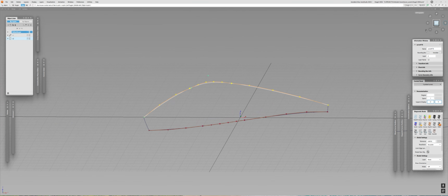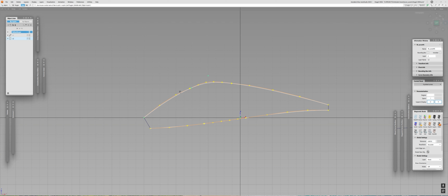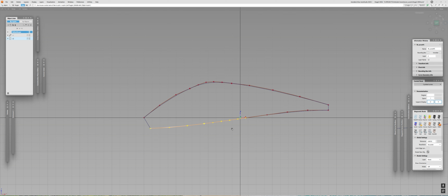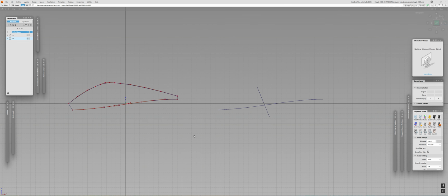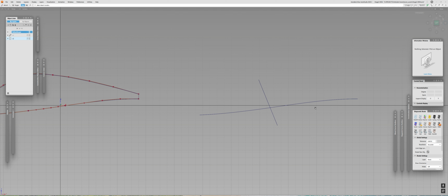But what's important here is that these parts are cut at a very specific parameter. Let's say it was parameterized. Sorry, let me move the wire a little bit away. Okay, so it's cut at specific parts. And first of all, it's not just detached. We have a specific tool in Alias called detach, which you're going to use to split your curves into 2 different parts, and they will maintain continuity.